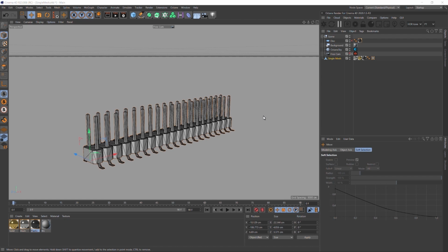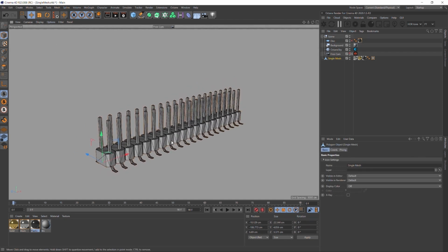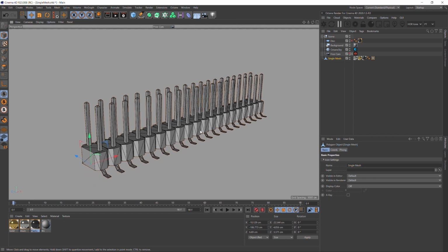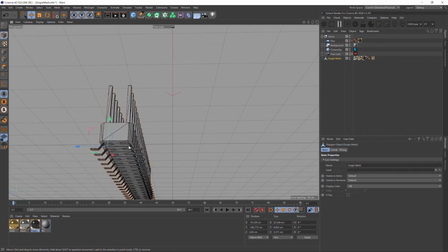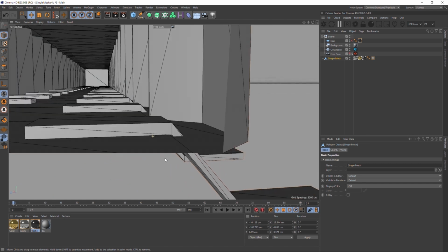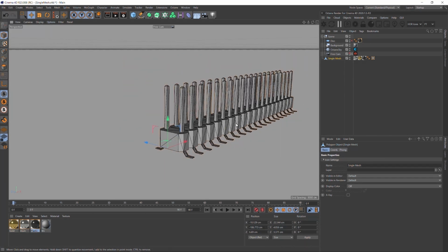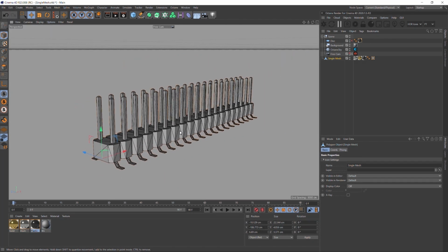All right, so we only have time to talk about one more thing, unfortunately. Now, this is another thing that I deal with quite often, and that's when your meshes come over and they're not supposed to be a single mesh. Originally, when this was created in CAD, these tails were separate pieces, and you can kind of see those start to bleed through. If we look inside the model, they don't share the same internal volumes within themselves. So they should have come over as separate objects. And most likely during the import process, they weren't set to by topology. So let's go ahead and show you guys how to fix that.